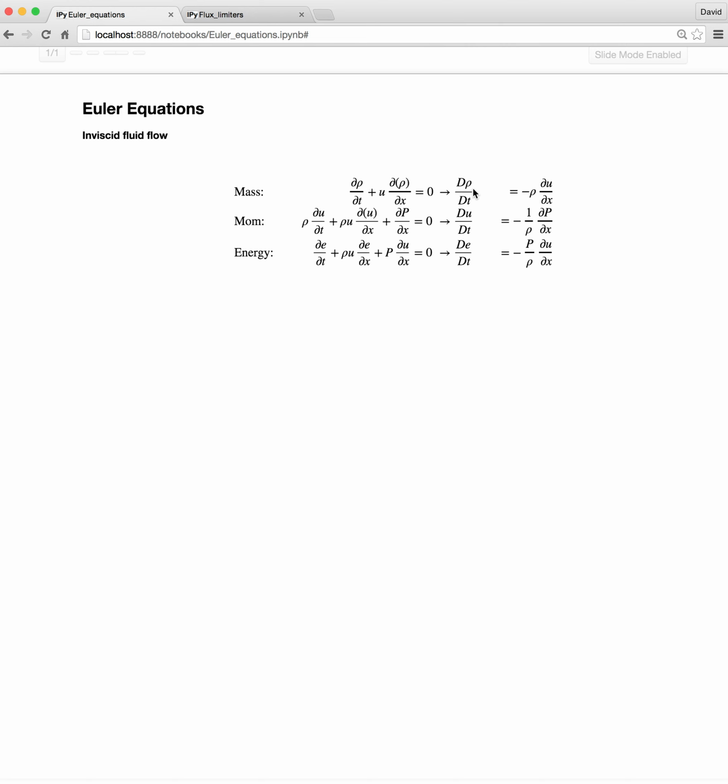The first thing we want to do to work with the Euler equations is to just rewrite the energy equation in terms of pressure. The easiest way to do this is to take the ideal gas law, where we define pressure as P equals rho RT, and then if we take the derivative with respect to that, then we get this dP dt is RT d rho dt plus rho R dT dt, and we can rewrite the temperature with respect to time in terms of the energy.